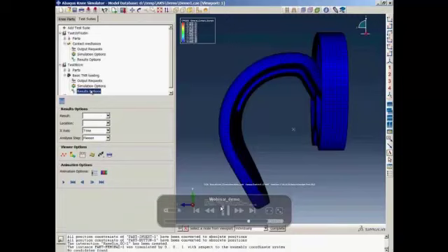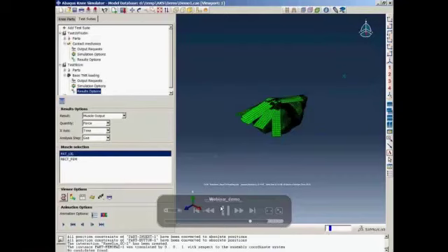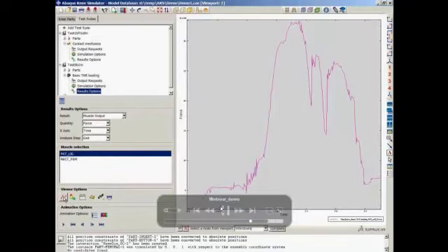Next, we move on to the visualization of the basic total knee replacement workflow. In this case, there are more output variables available for different loading conditions. In this case, I choose the muscle output, plot the force over the gait cycle, and I pick the patella ligaments. Then the outputs over time, over the gait cycle for this specific ligament, are plotted.